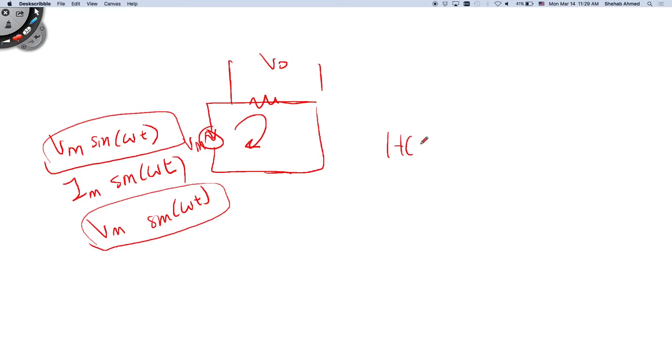So my transfer function, if you want to call it a transfer function in this case, is equal to V output over V input. In this case, it's equal to 1. Right? Whatever you put in will be whatever you put out. So there's no frequency dependence of the output. So yes, it's a transfer function. It is a ratio between any quantity at the input and any other quantity in the circuit. You can find the transfer function between any two quantities, voltage and current, switch opening time, and current.